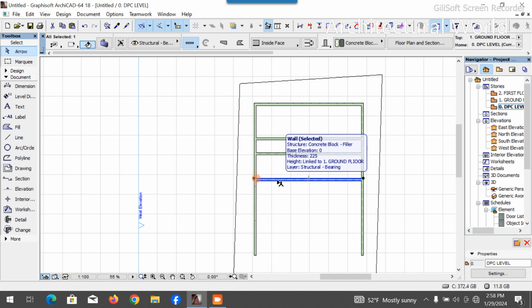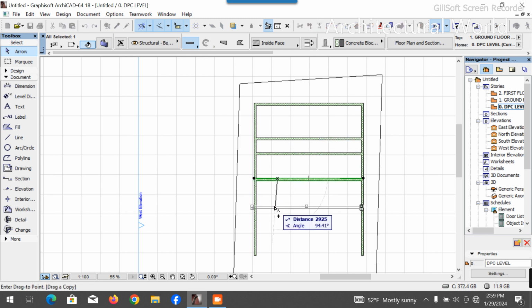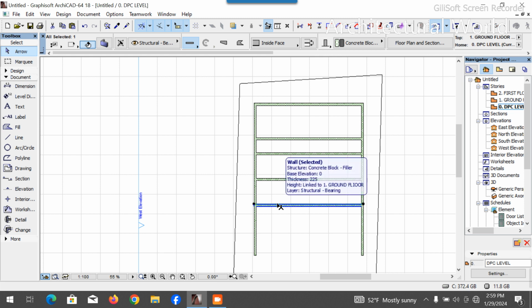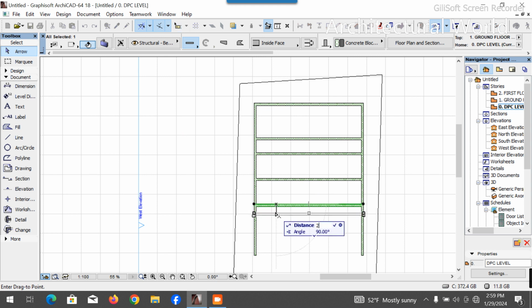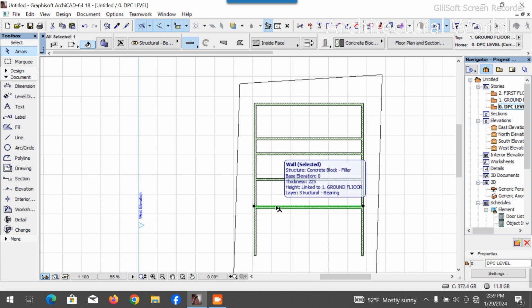Now, what is next? The next thing I'm looking for is my anteroom. What is the anteroom? The mini parlor that I explained earlier. I want to make that anteroom 2.4 meters in width and square. I want everything to be square. So I'm going to duplicate this wall to 2.4 meters. That's 2625. Okay, I can just decide to make this 2.8 since I have a large area. So I'll bring this and add 200 to it.